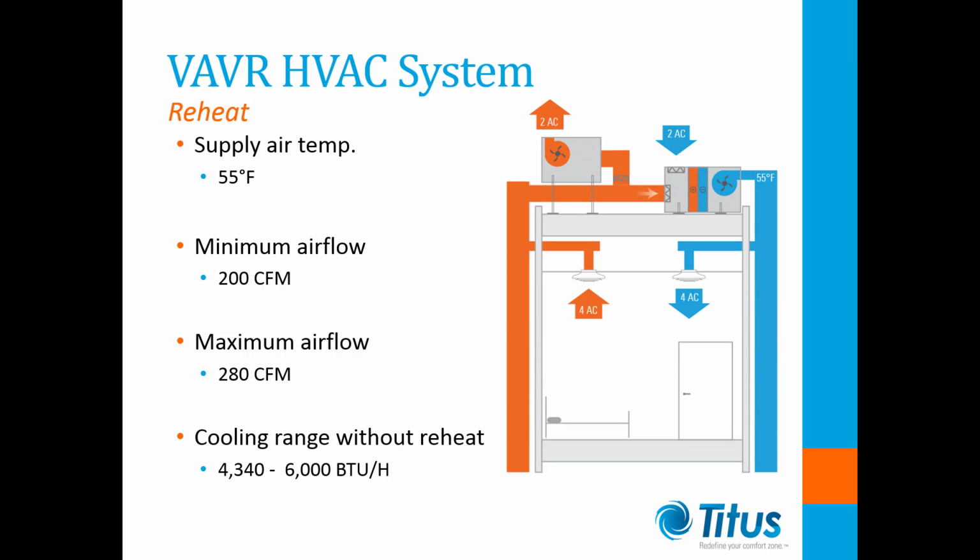As the amount of cooling air is 80 CFM more than the required ventilation and recirculation air, a VAV unit would normally be used to vary the airflow between 200 and 280 CFM, but it cannot turn down to below 200 CFM.